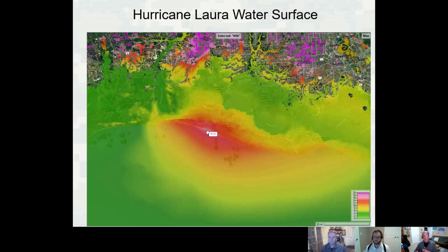Now, I do want to point out, RAS is only modeling the winds. Currently, we're not modeling the pressure forces of the air, okay? And we're not modeling wave forces, which ADCIRC does model. So ADCIRC's a more complete model of what's happening on this coast. But it's pretty cool that you'll be able to kind of do dual modeling where you combine ADCIRC and RAS for coastal projects, and you have the wind forces in both models.